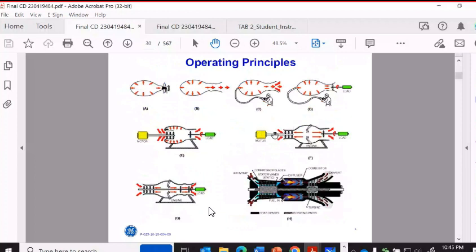In this picture right here, we had the compressor, and then this was your high pressure turbine, but there was no shaft. In your application, the shaft connects both the high pressure turbine and the compressor. By maintaining fuel flow and airflow across here, the rotation of the high pressure turbine operates the compressor section. So it makes it self-sufficient at that point.